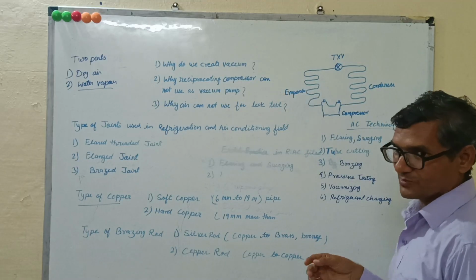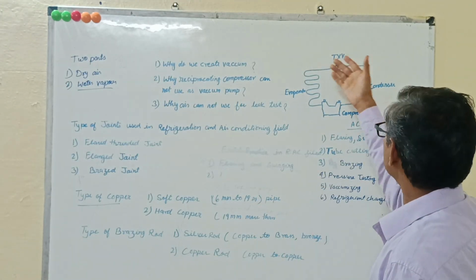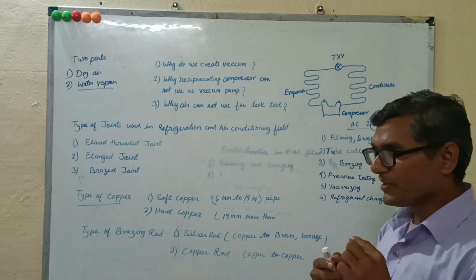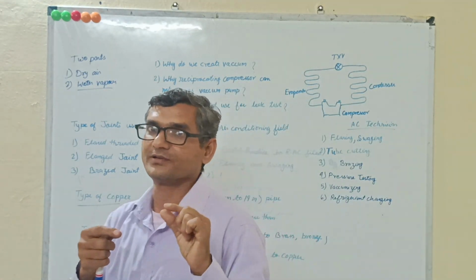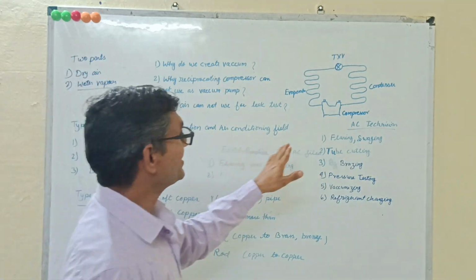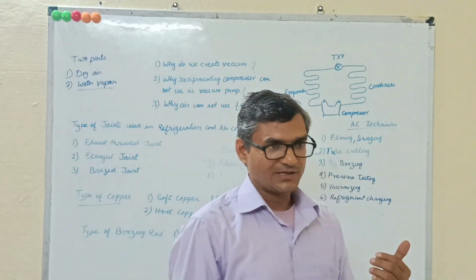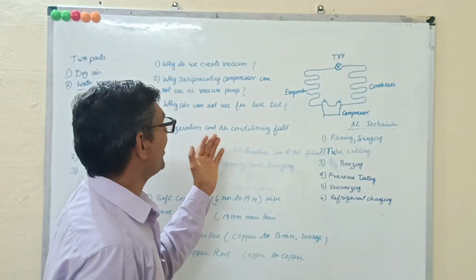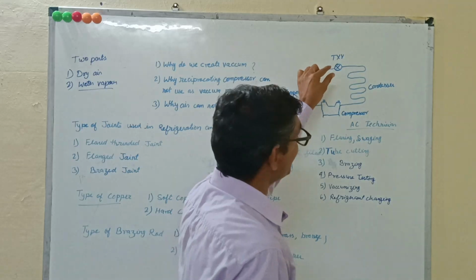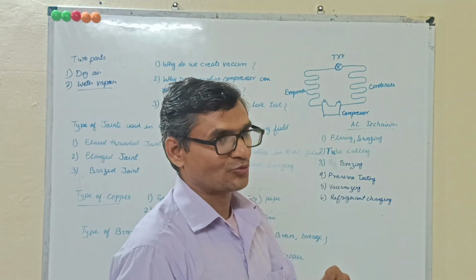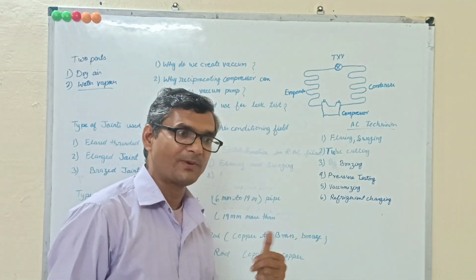Without creating a vacuum, we have charged the system. Then what happens in TXV systems? There are very narrow holes, called an orifice. When refrigerant goes there, it boils at a very low temperature. Then moisture is there. Moisture, when cooled, converts into liquid, and if cooled again to a very low temperature, it goes to minus also.